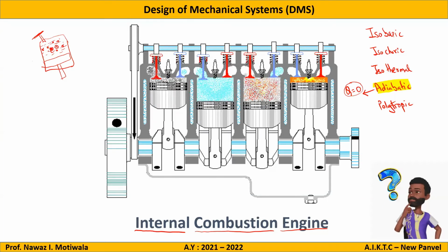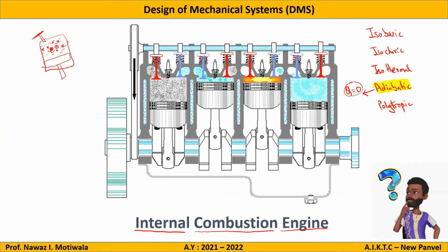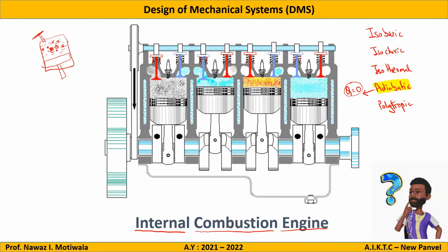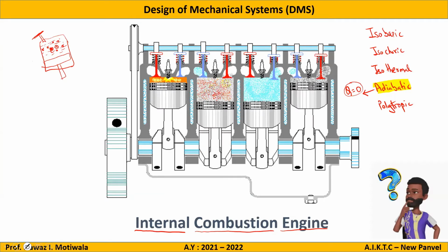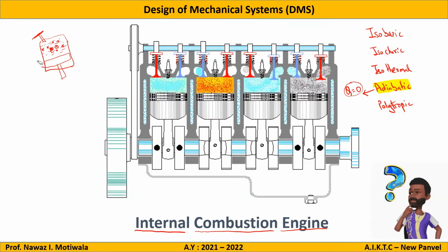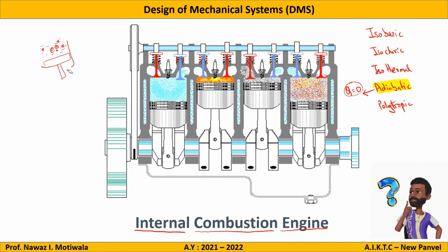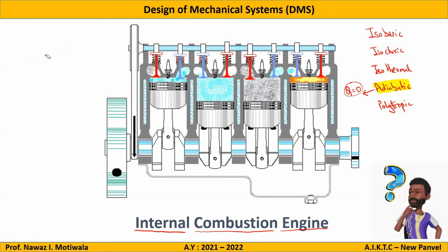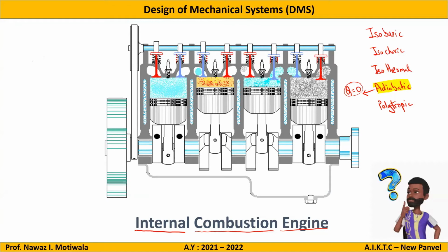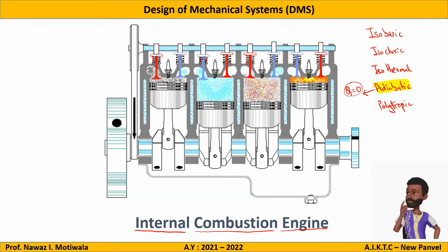That's the only point which I want to prove: just seeing the PPT and putting all the things on the slide does not work. When we discuss, we come to know the different things which we are lacking about. So I hope now you will not make a mistake henceforth, that if I tell you that it is an adiabatic process, you will just say the transfer of heat is zero, not that the temperature rise is zero. So adiabatic process is also known as what?